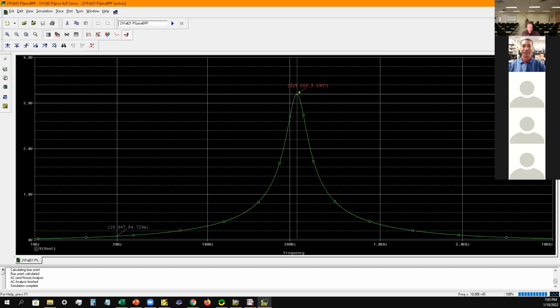Okay, that makes sense, it's the maximum. Yes. So you look at the frequency, and then you take whatever the maximum is here times 0.707. That tells you where you're going to be at your cutoff frequency, which is about 2.26. So somewhere over here, 2.26. Somewhere in between here, somewhere right here would be the cutoff of the first one.